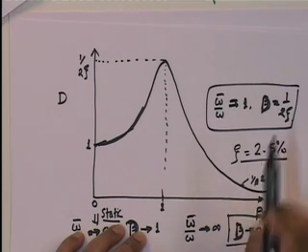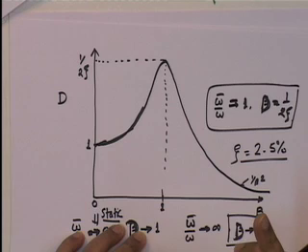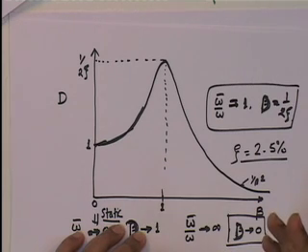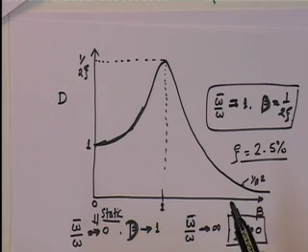So, for a 2% damped structure, dynamic amplification at resonance is 25. For 5%, it is 10, still very large. Therefore, at resonance you have large amplification of response for harmonic loads, for any kind of normal structure. As I said, in normal structures the damping is always less than 10%.